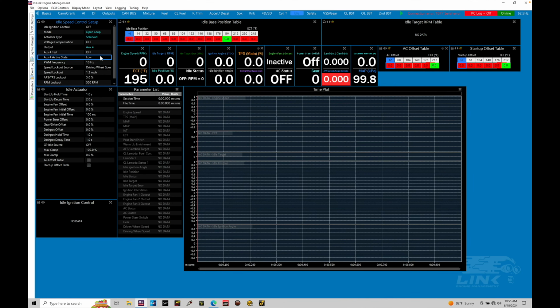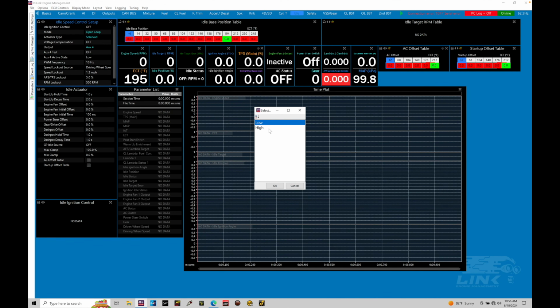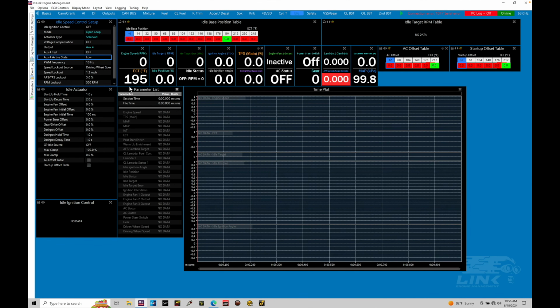The other wire will be a pulse width modulated low side pulse, where we're ground pulsing the solenoid. Again, you could theoretically wire the solenoid so that it's getting a constant ground, and then you're sending a high side or 12 volt pulse. I'm going to go ahead and just make sure I'm selecting low here because that's how a Honda solenoid is typically wired in the OEM wiring harness. Now we have a frequency we need.